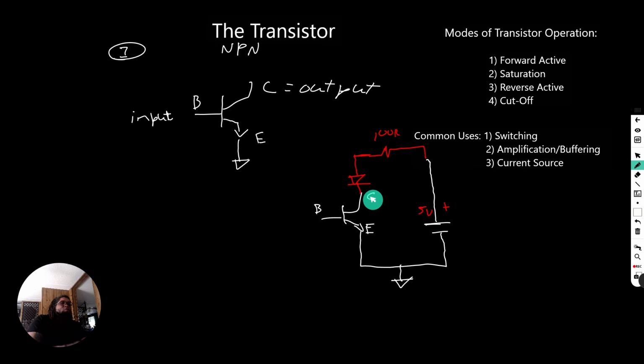It does, and on one end it's grounded. But why, if this transistor has positive voltage on one end going through this resistor and LED at the collector, and its emitter is grounded, doesn't it see enough voltage to turn this on? Well, the answer is that there is voltage present at the collector, or nearabouts,